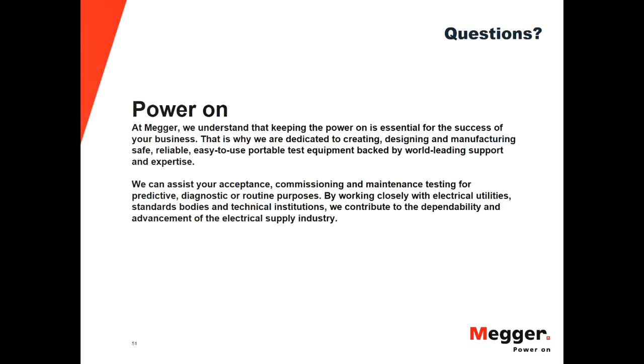However, this is not going to be always. You could have a battery under that condition with no capacity or in very bad condition, but the ohmic value is going to be the same as when it was new. So it's not such a reliable test for nickel-cadmium in certain cases. So I guess that's my thinking about why they removed it from there. Thanks. All right, next question.